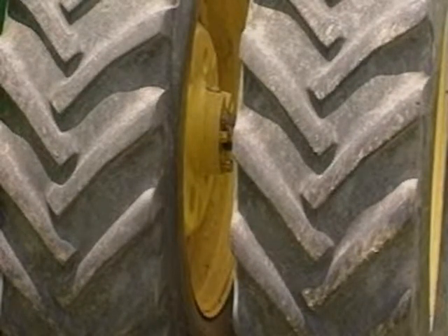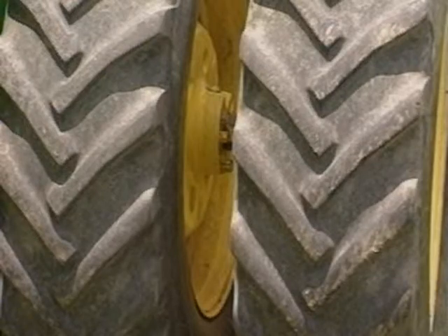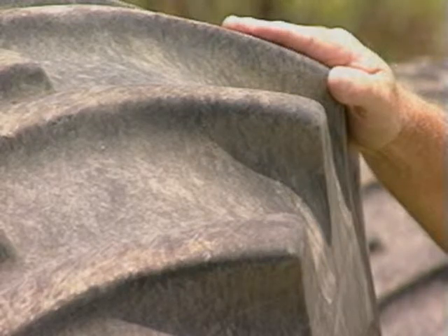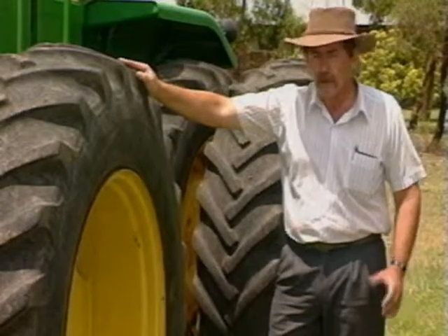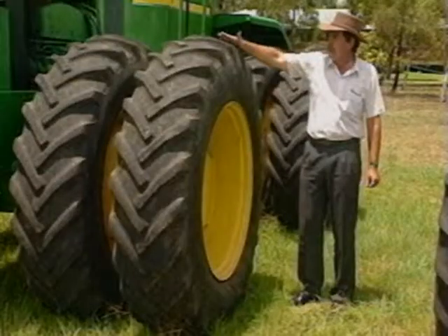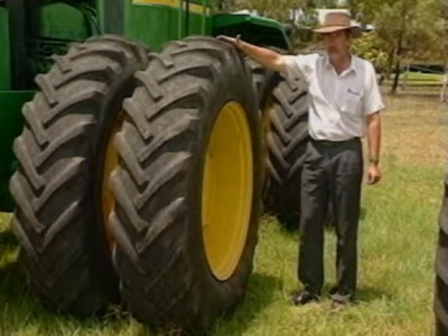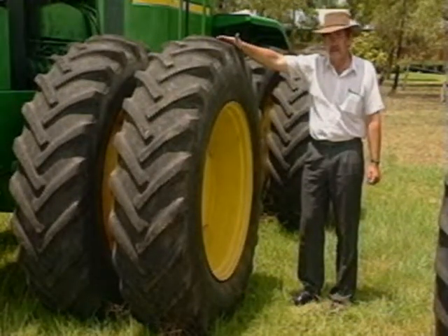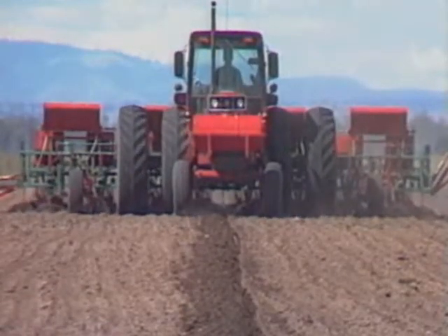The second factor, do we use duals or do we use singles? If we can do the job on a single tyre operating at a pressure acceptable to the load, then we must use single tyres. We see a tendency in a lot of cases to over-tyre a tractor in the belief that a greater amount of tractive efficiency is going to be gained. This in a lot of cases does not happen when we put a dual on when we don't necessarily need it, and all we do is carry around an extra tyre, and in a lot of cases we reduce our tractive efficiency because we're increasing our rolling resistance of the total package.